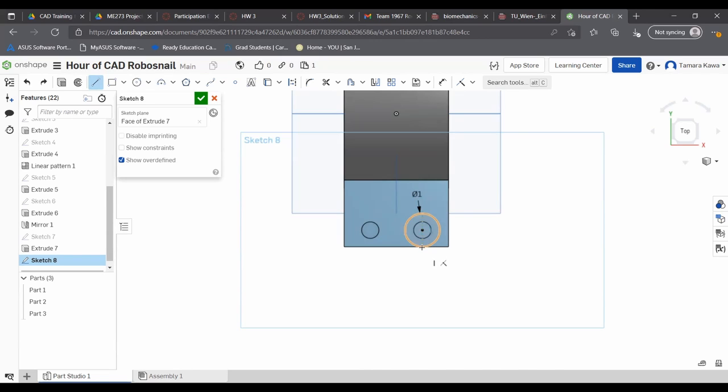So that's one way you can make your lines vertical. Another thing you can do is, of course, just take your line, go like that anywhere through. And then I can select this point and this line, make it coincident. And then I can drop down, use vertical, click on the line, and there you go. So either way, you have a line.